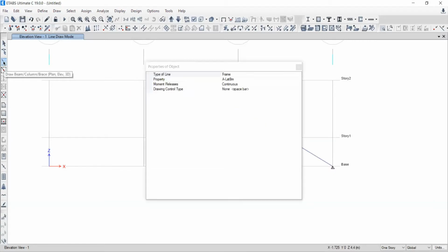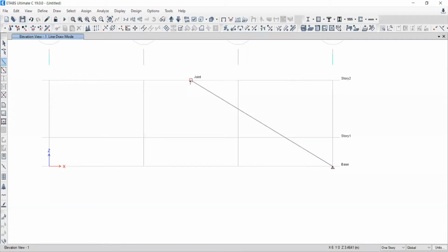But if I take the frame, now close it. I'm taking the line from here to here. Now I have to take the line again from this point to this point. I will take the help of this continuity and the active command. Click over that. Now I don't want to draw the line here. I would like to draw the line from here to here only. So I need to stop the continuity. So right click, continuity will be stopped. Now click on this first point, the command is active. Click on this first, move to this. This is done. Clear or not, Pratik?